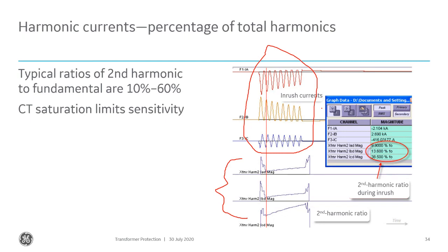One of those modes is per phase, and that's what I showed on the slide earlier in the presentation, and I said that's probably not a good idea. And that's how electromechanical relays operated. Because they were phase segregated relays, they operated per phase. We don't want to do that, because if we did that on this particular transformer, we'd trip on A and B phase, because A and B phase both drop below that 20% value.